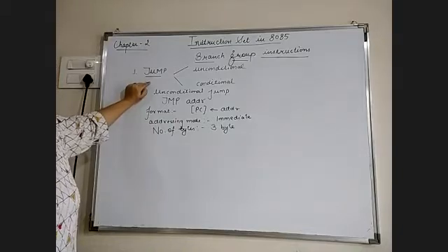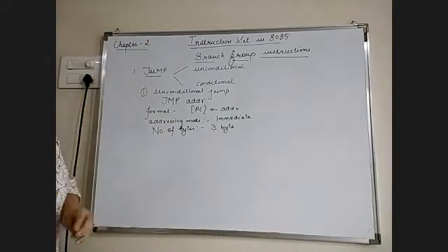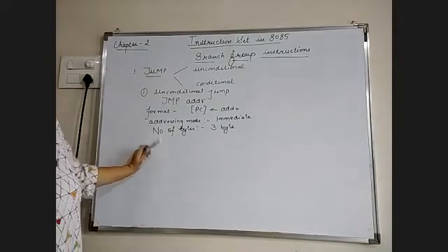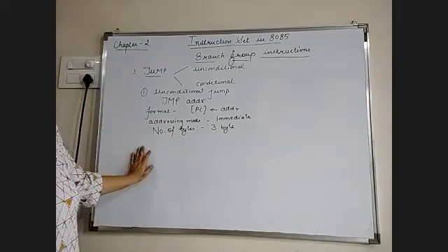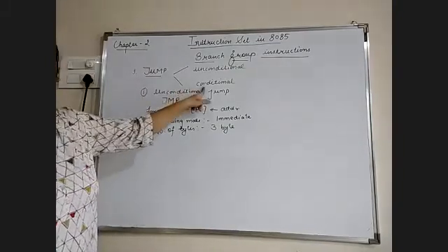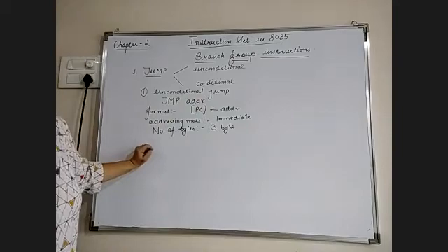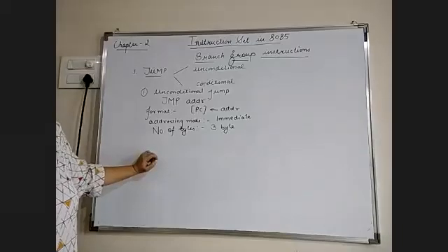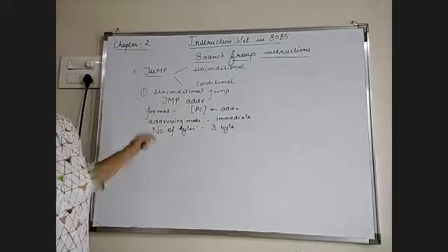Okay, so jump statement is the branch group statement. Jump statement is of two types. First is unconditional jump and second one is the conditional jump. Unconditional jump is the statement which microprocessor can execute without checking any condition. Directly when this instruction comes in the program, microprocessor will directly jump to that particular memory location which is given in the instruction. But in case of jump conditional statement, when the condition is satisfied, only then the microprocessor will jump to the memory location. If the condition is not satisfied, then it stays in the main program and it will execute the next instruction which is after jump statement. I will tell you this with the help of example.